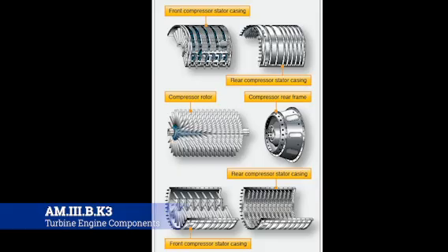With this increased velocity, energy is transferred from the compressor to the air in the form of velocity energy. The stator blades act as diffusers at each stage, partially converting high velocity to pressure. Each consecutive pair of rotor and stator blades constitutes a pressure stage. The number of rows of blades, or stages, is determined by the amount of air and total pressure rise required.